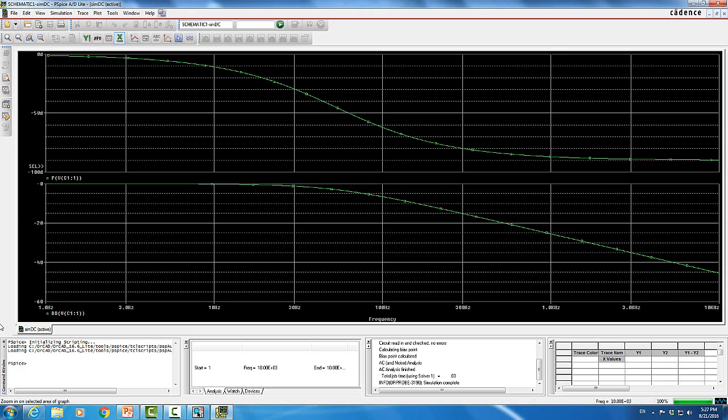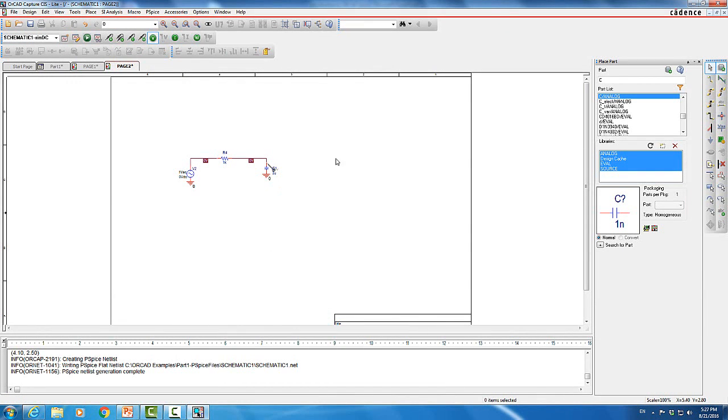Computer simulations basically here will tell you what the frequency responses are. Now we're gonna do a transient response. So there are 2 voltage sources I will apply for the transient response. So what I'm gonna do is I'm gonna come back to the same circuit. I will click on this AC voltage source, I will delete it, and now I'm gonna add the sine wave.